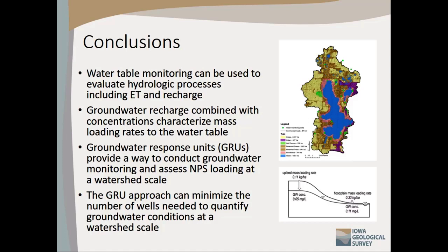How about barometric pressure fluctuation influence on the water table? And these, there would be none because they're all vented transducers, so they're already equilibrated to barometric pressure. I've got to say, when you use non-vented ones, I'm not sure they're sensitive enough that some of those corrections, it seems like they kind of mess with that signal a little bit, because if they're not on the mark, you know, that gets lost. So these were vented transducers, which made that a lot easier.